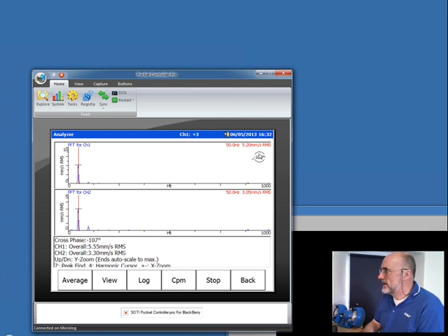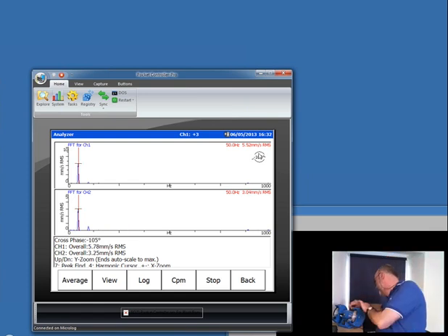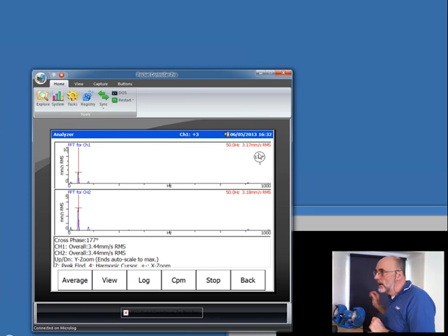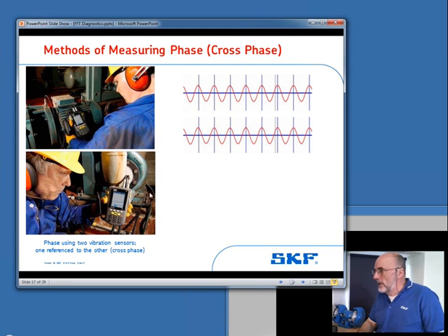And you've got your phasor plots. If I move the sensor by 90 degrees, there we go. They're now 180 degrees apart, 178. So the 2 sensors are now opposing each other, and are getting a 180 degree phase difference. So while we were there, we just had a quick look at unbalance.